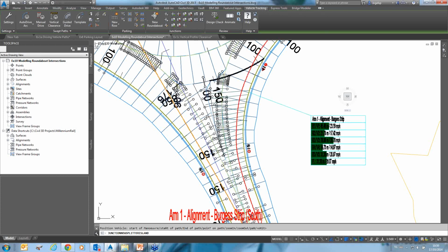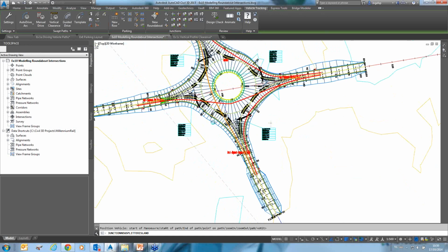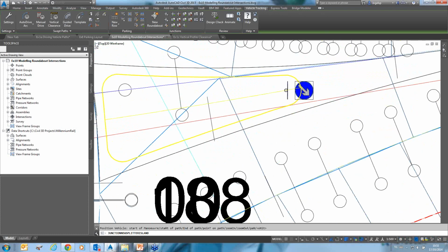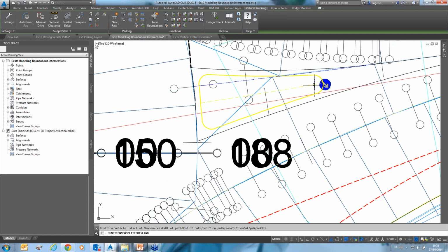If you want to add an island in the junction, so basically in this leg, or let me take another one to see if it's a bit better. Yep, here you add an island, so it will automatically create the geometry for you. So this yellow line now is the island between the two lanes. Okay, there it is.